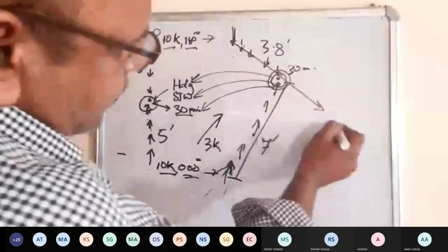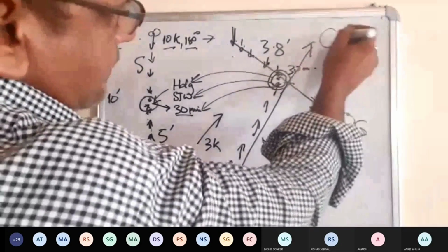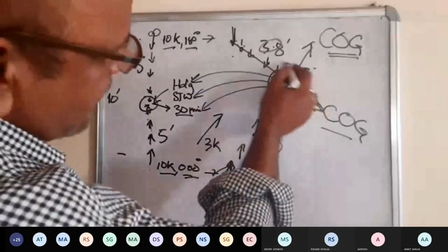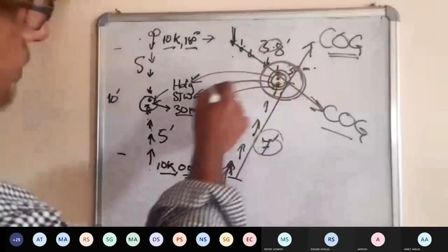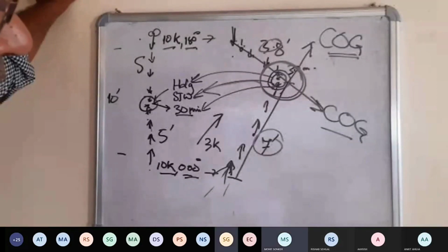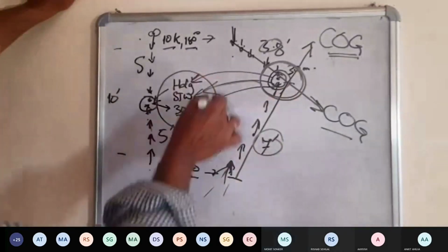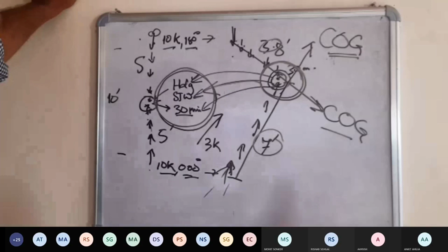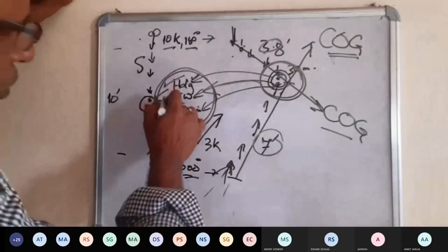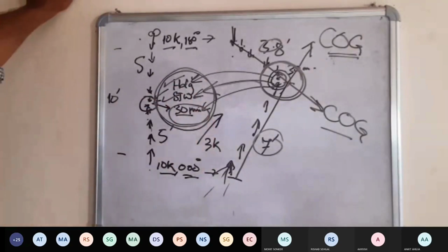The course COG is like this. The course here is like this. This course over ground, the speed over ground, did it make any difference in the collision situation? No, they will still collide. Yes, sir. But for collision avoidance, this was the main reason for collision. If we wanted to avoid collision, we had to look at the heading, we had to look at the STW. That will of course decide the minutes before which it is happening.